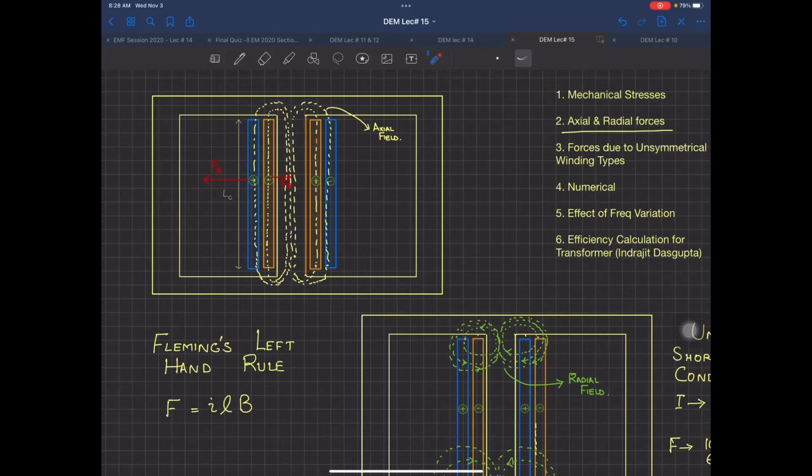Now you have done PSP, you are doing your PSP course, and you have been told that whenever a generator is going to be short circuited, in the very first few transients you are going to take the sub-transient reactance, and then you are going to calculate if it's going to be a 3-phase short circuit fault with respect to ground, then you are going to have all 3 phases short circuited.